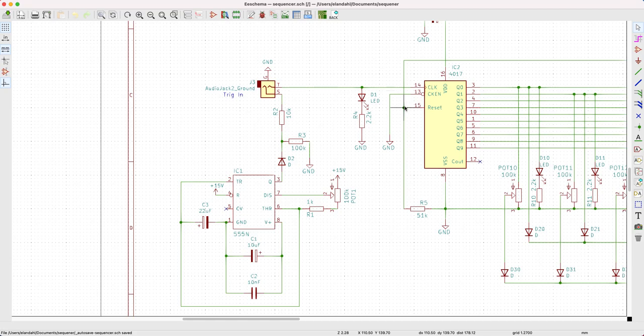A few other details. The reset, like all the inputs to these CMOS chips, always needs to have a signal connected to it. There is an enable, which needs to be set permanently low to ground for the chip to run. There is a reset, which we're using on the off chance that we don't have one of these connected over in our jumper.